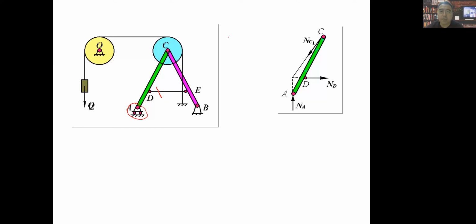So that's why we call that FBD, because the first letter F means free. So this process is first we should free this body, free this object from here to here. This free process means we will remove all the constraints at different points.